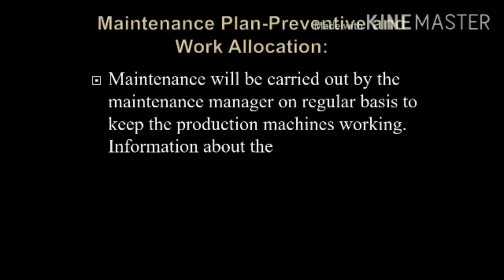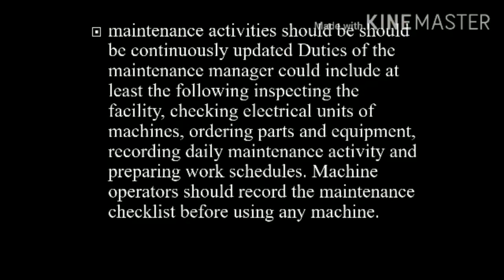More than that, maintenance activities should be continuously updated. Duties of the maintenance manager could include at least the following: inspecting the facility, checking electrical units of machines, ordering parts and equipment, recording daily maintenance activity and preparing work schedules. The machine operator should also complete a maintenance checklist before using any machine.